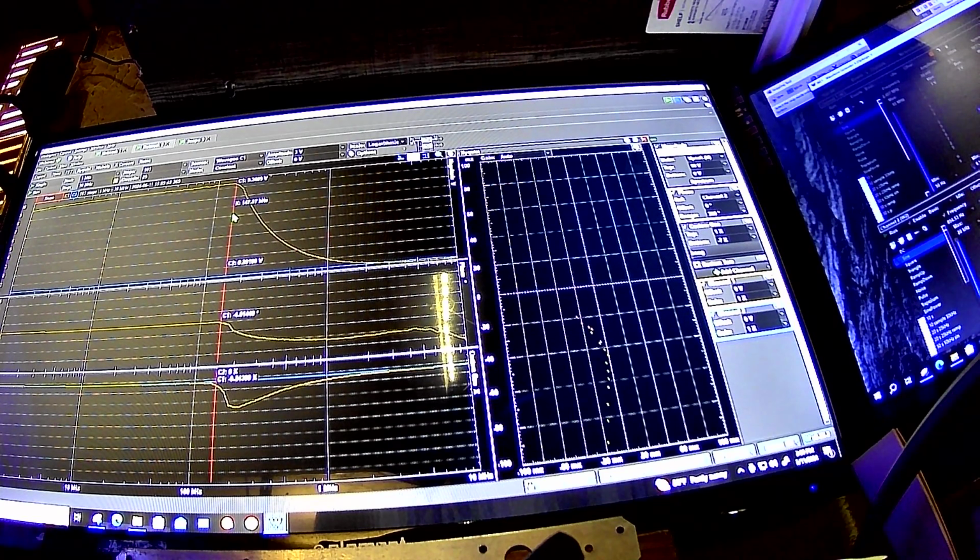But you've got to set both your probes to 10x and not tell it that. I tried changing these settings when I paused the video, but I couldn't figure out how to do it. For a 10 volt signal, which is a 20 volt peak to peak signal, amplitude just means V peak, not V peak to peak. So when I've set it to 3 volts, it's really putting 6 volts peak to peak, and that's being multiplied by our 3x amplifier, giving us approximately 18 volts peak to peak output. Again, that's a good approximation of our power bandwidth.